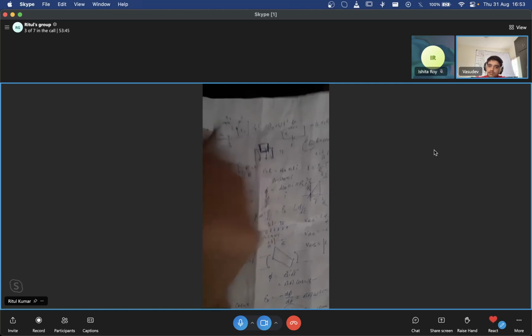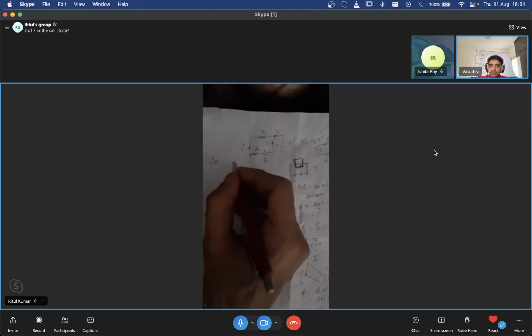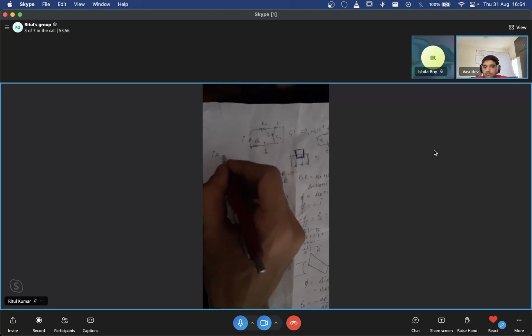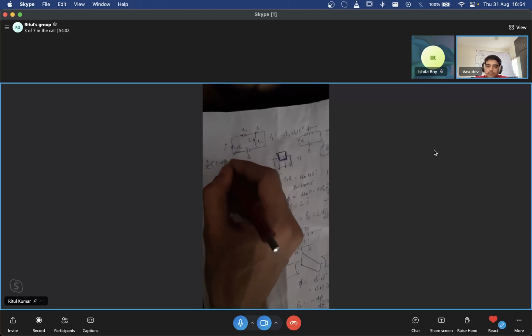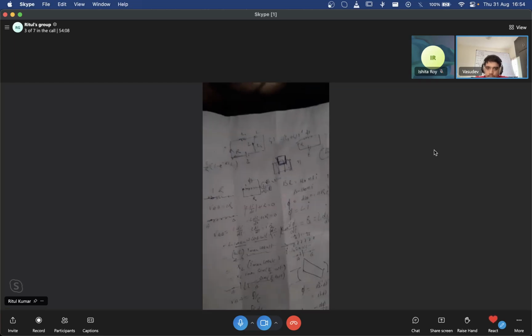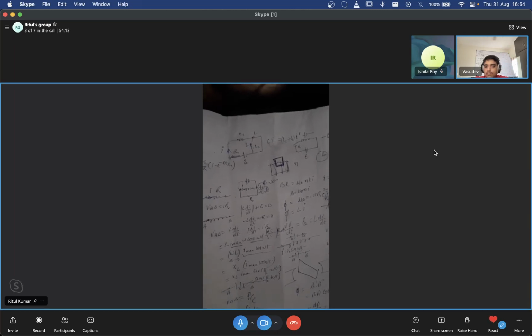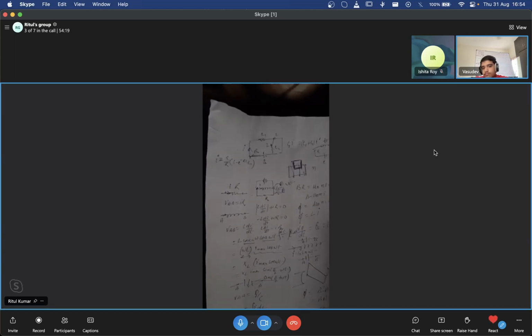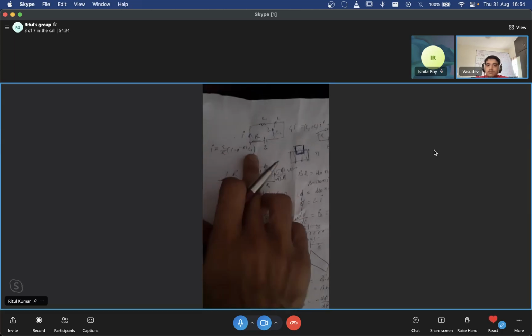When I have flipped it, okay? At that time, if I was asked, tell me what will be the current as a function of time, let's say it's not steady state. Then what would have been the current given to me? Equation-wise, E by R into 1 minus e raised to the power minus RT by L1. This would have been the current. So this current was flowing at T equal to T, and that is the time when I decided to switch from position 1 to position 2. It is not steady state, I'm taking an arbitrary state. This is the current flowing through it.